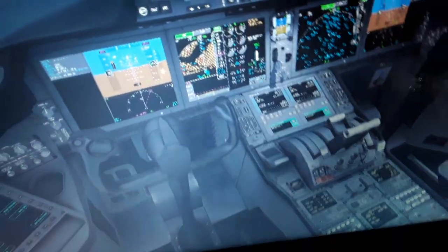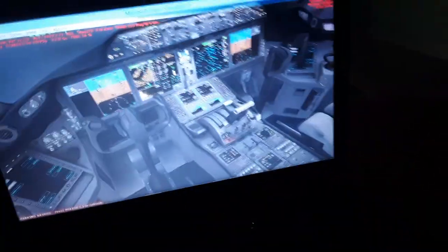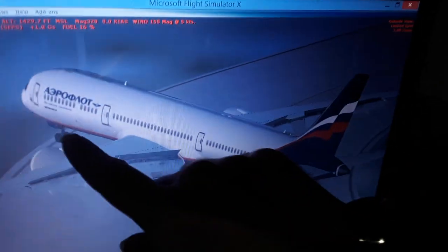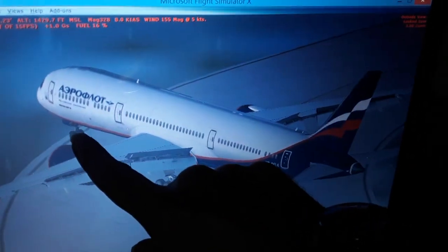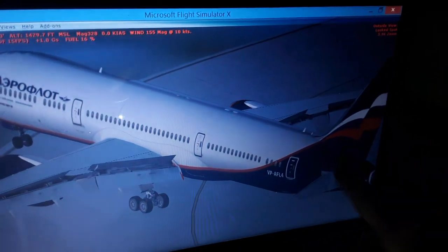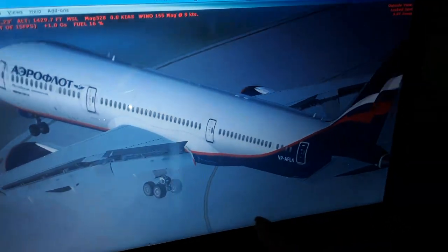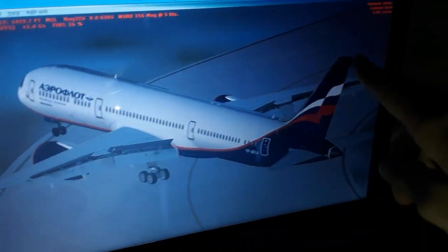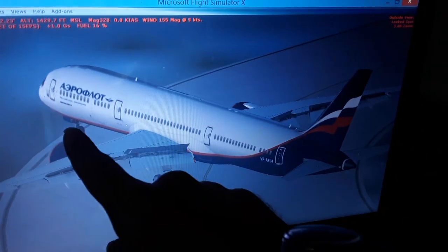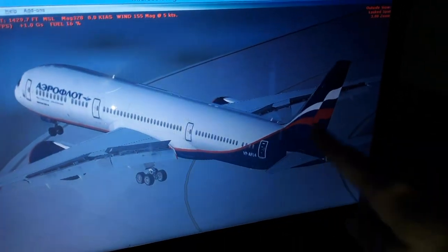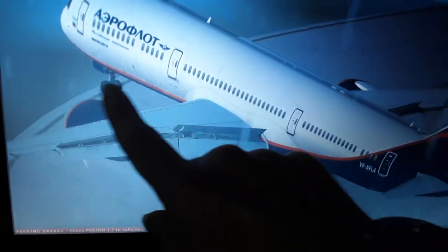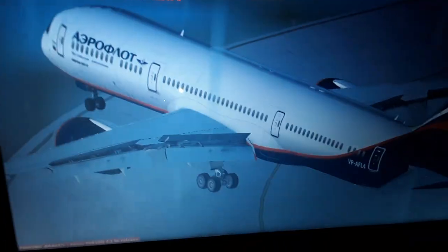So it's very easy. I have it also in my side stick. So we use also the forward nozzle. It's controlled automatically from the computer together with the rudder, from 0 knots up to 45 knots, like in takeoff or in taxiing, like 80 kilometers an hour, 72 kilometers an hour. The forward nozzle will deflect up to 76 degrees, also using the tiller.